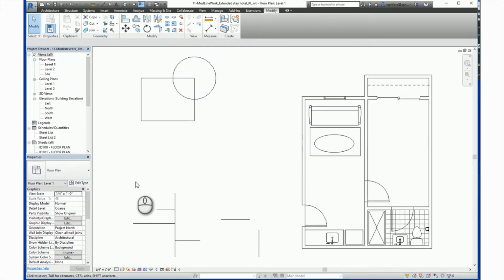The Mirror tool allows you to mirror elements across an axis in order to create a mirror of an element or multiple elements. You can select an existing reference line using the Mirror Pick axis, or draw a temporary axis using the Mirror Draw axis as you mirror an object. The tool is used to flip a selected element or to make a copy of an element and reverse its position in one step. So as I mentioned, there are 2 tools.